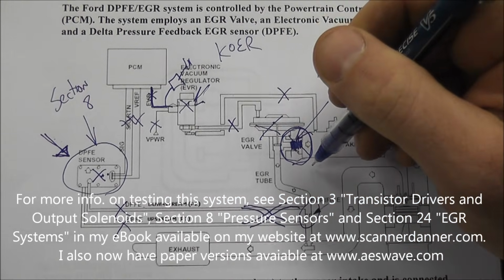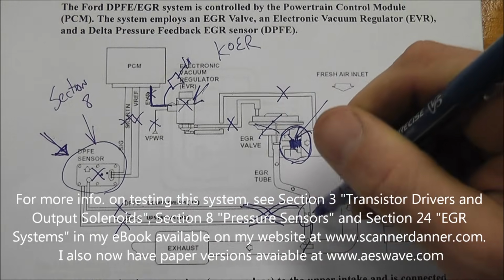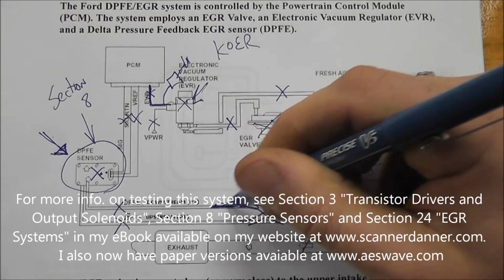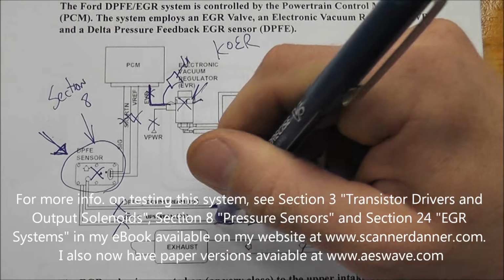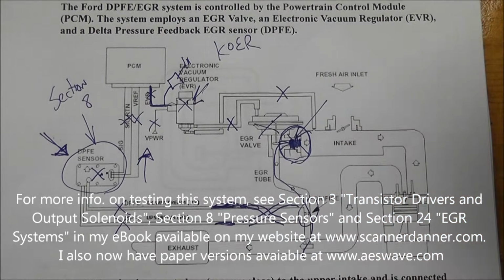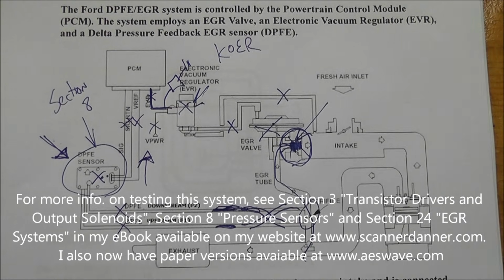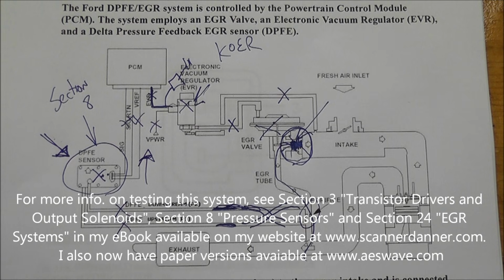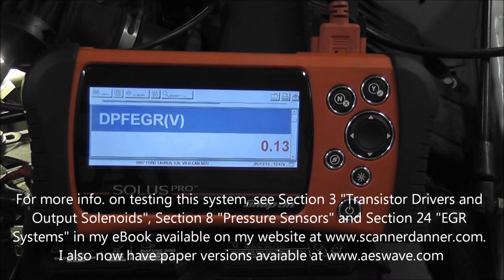If the engine gets rough and just about stalls, that means we have flow taking place in our tube, and that means we should have a difference in pressure in the top tube compared to the bottom one, and we should see a DPFE signal rise. This is what we're going to do first. All we need to do is T-pin, test light to ground, engine running while we're watching scan data, DPFE voltage, and listening for the RPM to get rough. So that's the test. That's what we're going to do. Okay, so back on the car, looking at our DPFE voltage.